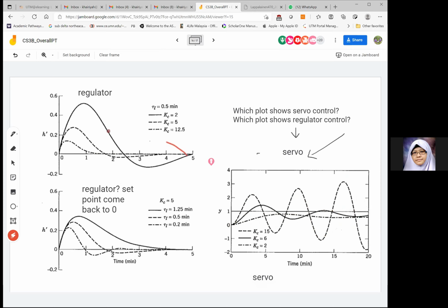On the other hand, this is PI control. By the way, PI control makes it easier to have an oscillatory response because of the PI controller. P control can usually be fast, but you will get offset, and it is more difficult to make it oscillatory.